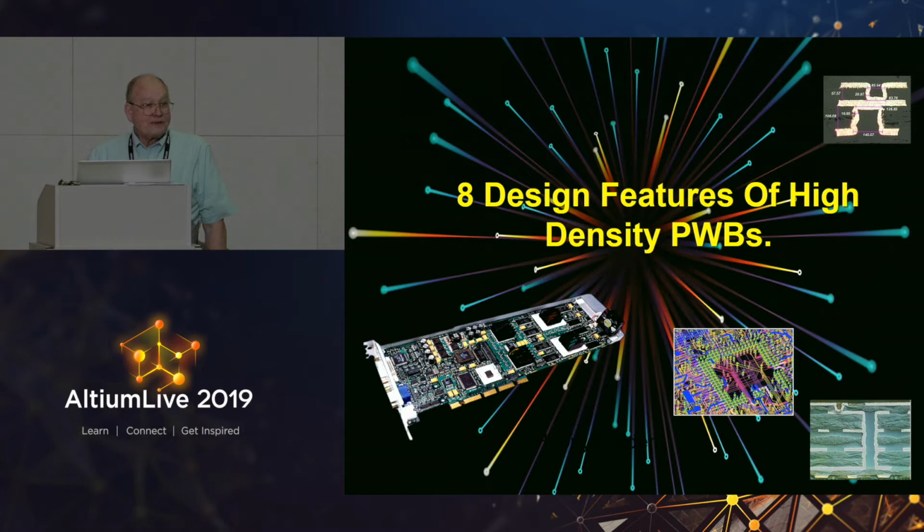Like IBM, in Hewlett-Packard, we didn't patent all of our greatest ideas because you have to disclose so much information in the patent that everybody understands it and you can do a workaround. So what you do is you just keep it a secret. You would wonder that sooner or later somebody would take apart Hewlett-Packard computers or instruments and figure out how they are doing this. And they would realize, we don't have any power planes. Well, how can HP do this? How can they be at 80 gigahertz and not have a power plane? Well, because it's RF circuitry and we use coplanar power delivery.